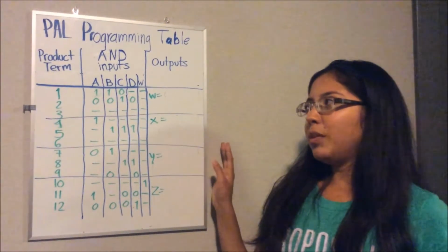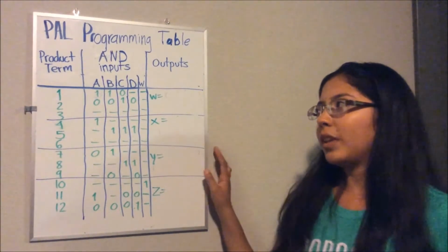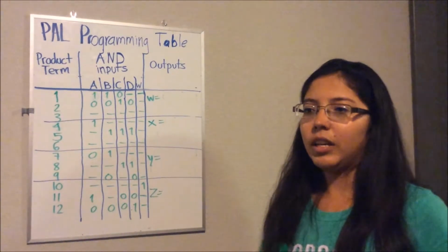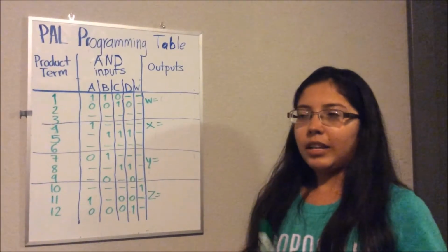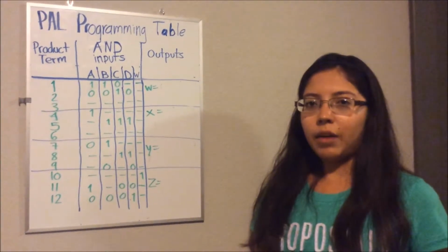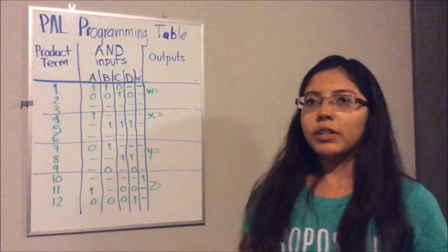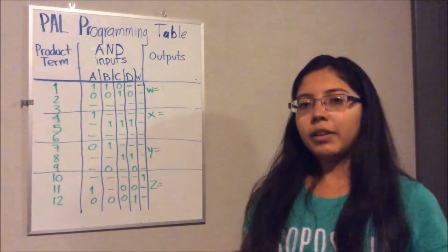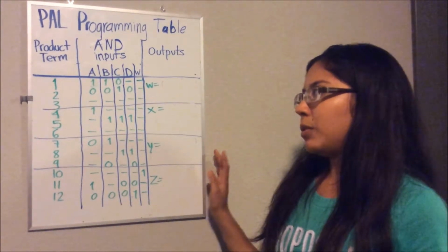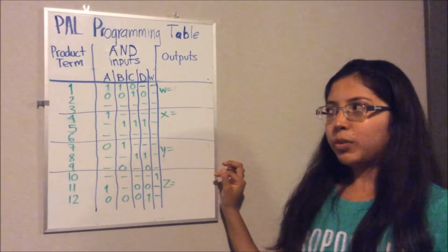This is an example of how a PAL works. Generally, a PAL has 8 inputs, 8 outputs, and 8 sections. Each output is gonna have a buffer or inverter to obtain the different results that will be given by the OR array. In this case, we're gonna have 12 inputs and just 4 outputs.